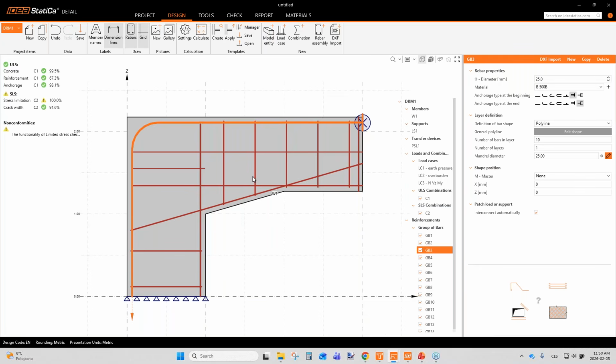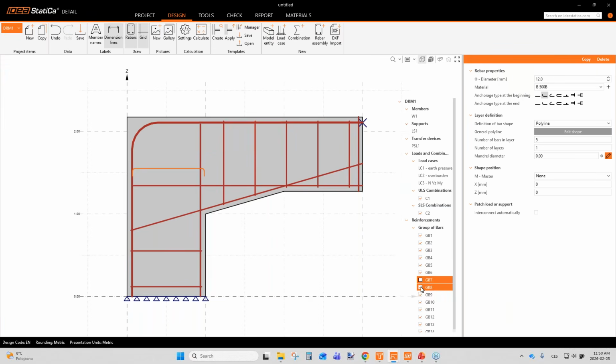As I was showing in this example, when I removed those rebars and I had a big area of the frame corner unreinforced, I didn't know if the structure was cracking there or not. So this is a common thing that we see, that they do not add any reinforcement into some areas, and then they do not get the crack results there. So to avoid that, at least detail reinforcement even into the areas that do not appear to crack at first glance.